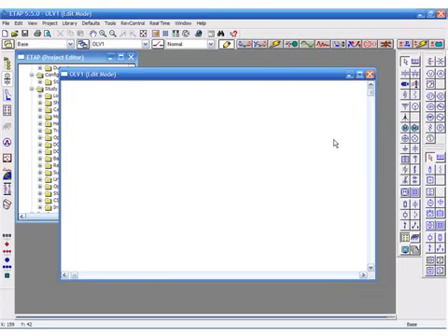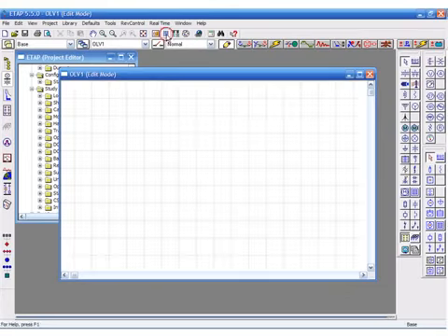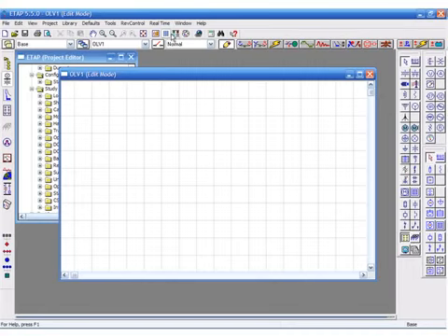You can turn the grid on and use it as a reference for spacing between elements, like this. Right next to it, you'll see our continuity check. Let's make that active. That way elements other than the power grid or utility are shown in gray when they're de-energized.